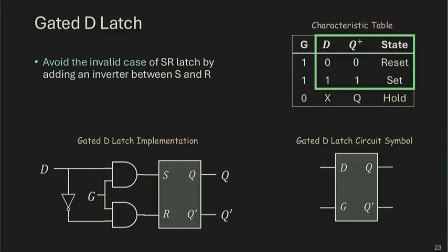All right. So SR latch supports 3 operations: set, reset, and hold. There's a different latch called a D latch that supports only 2 operations, set and reset. And with 2 operations, you only need a single input. We used to have 2 separate inputs, S and R, and you have to enforce a particular relationship on those 2 inputs. And for convenience, you can also implement a single input latch by using D as your set input and using R as the complement of D.